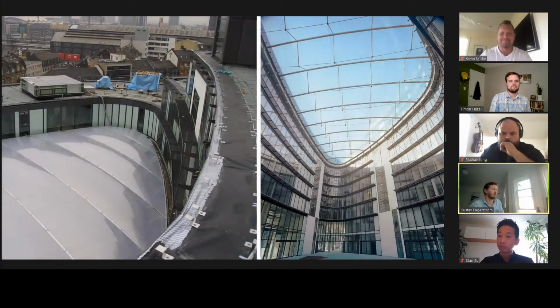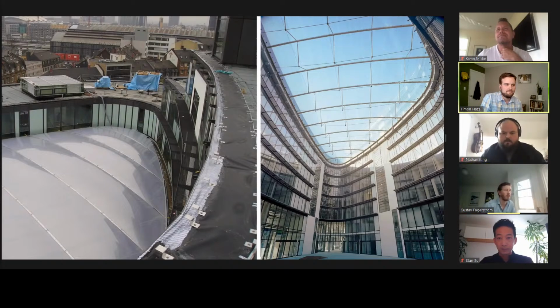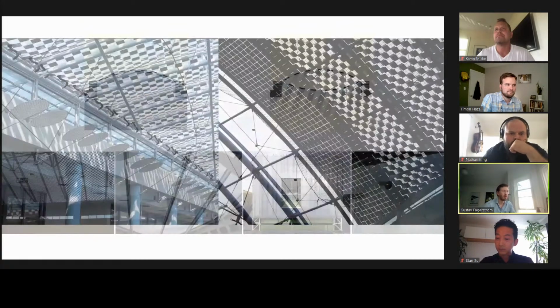For instance, when we observe that there is a consistent issue with film enclosures like the ETFE here, which has certain spanning capabilities, it has certain light transmission, leads to certain solar heat gain, etc. You can't low-E coat this because the metal sputter will destroy the ETFE. And what many times ends up happening in projects is that you coat them like this. You've got the frits and you've got your fabrics and you've got your actual visual obstructions, right? Which may look like this.